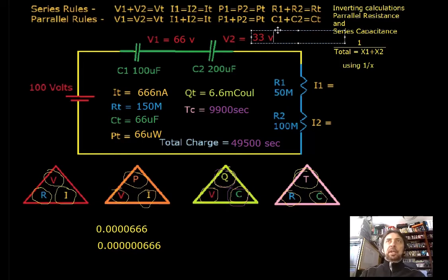So again, you can see how we calculate these circuits, and of course V1 plus V2 equals V total. That looks about right to me. Now in current, of course, being current in series, we can see there that the current should be equal everywhere. Whatever the total current is, basically that's what the current should be also at R1 and R2.